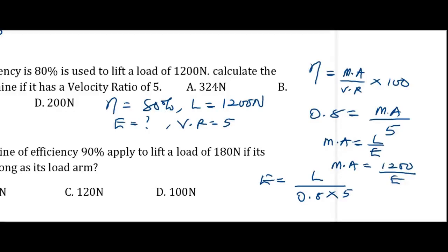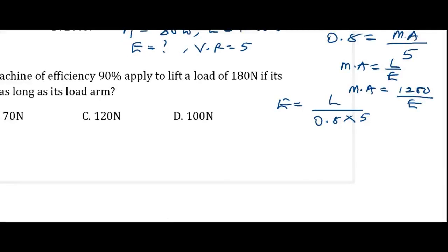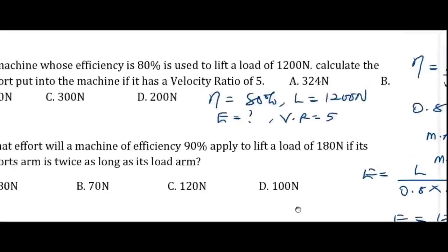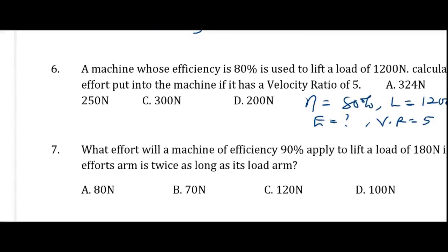So what is the load? Load is 1,200. So that will be effort equals 1,200 over 0.8 times 5. So the effort here is 300 Newton. So let's go back to that question. Therefore, option C is the correct answer.